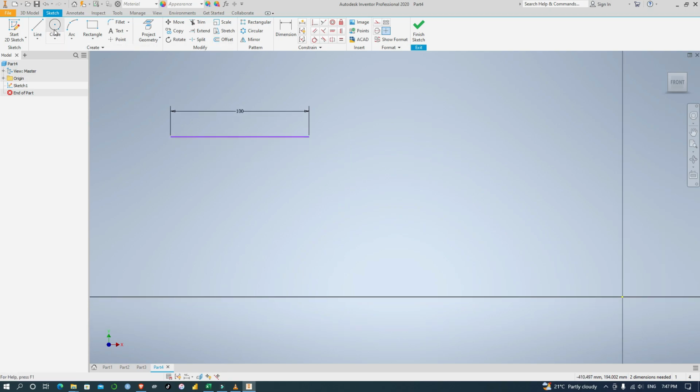Next, after drawing the line, you found that you drew a straight line. So let's try to draw a vertical line or a line at an angle, and let's say we want it to be 100. To put the dimension in degrees, you click tab on the keyboard, and it will tell you the amount of degrees you want to do. Let's select 30 degrees and click enter. So the line is 30 degrees to the horizontal.